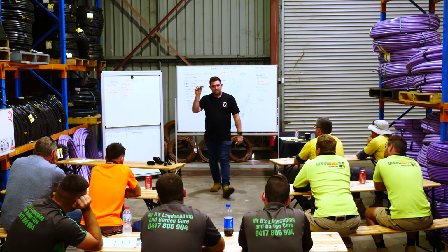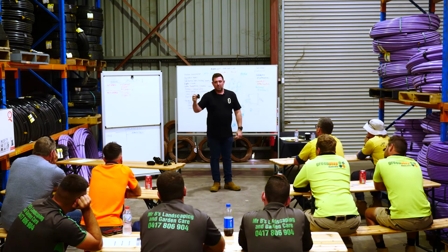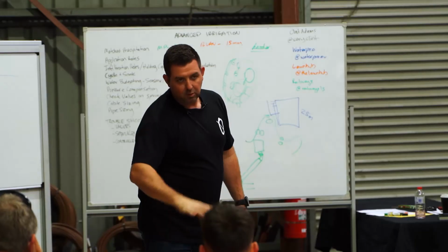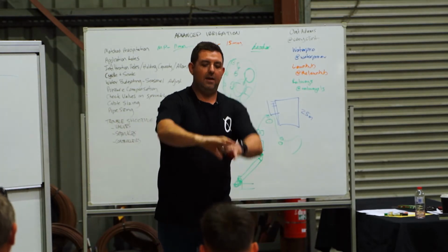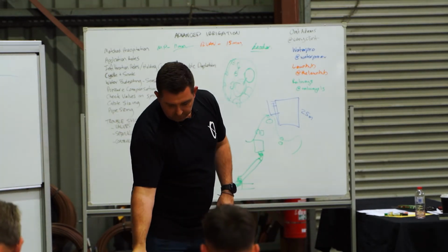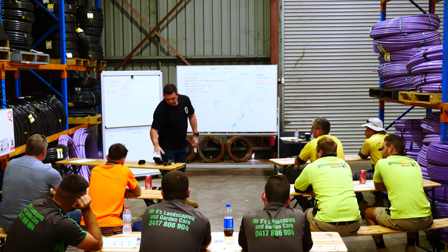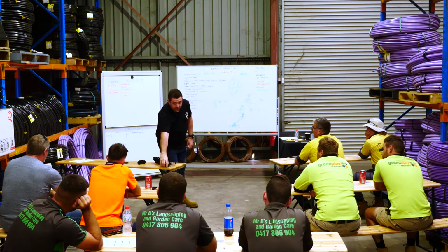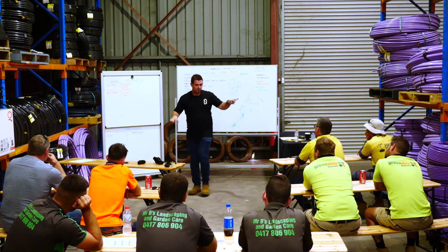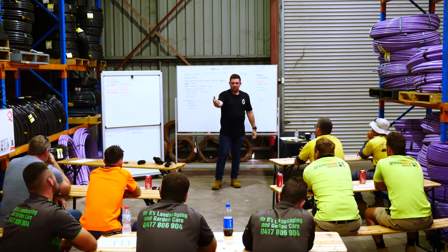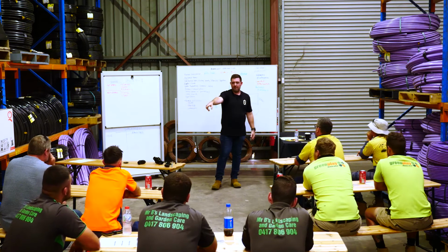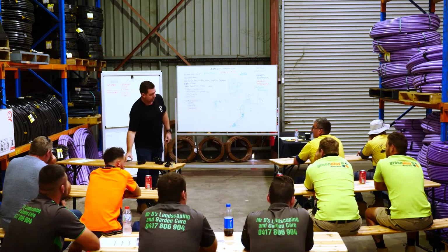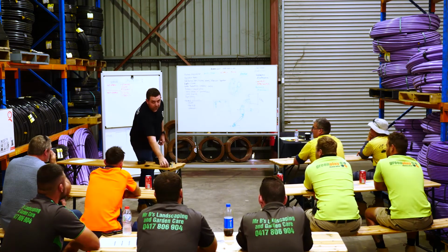We generally don't sell these as a spare part on their own because that plus that sold separately equals that. So what we try to do is encourage people to buy a solenoid valve, take it apart themselves, fix the diaphragm, keep that, and they've got 2 spare parts. The problem that occurs in that situation is that you're replacing, what did I say before? 80, 90% of a solenoid valve's problem is a diaphragm, and then 10 or 20% is a coil.